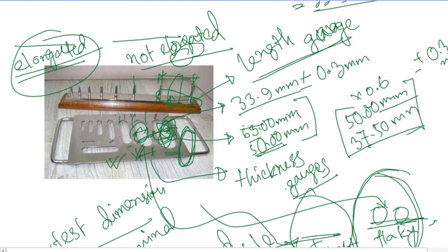So you'll be able to see and you'll not get confused while passing through. Just remember, you should keep every sieve fraction separated, so that whenever it is 50 millimeter retaining, you will pass it through this. It will be marked there, so don't be confused.